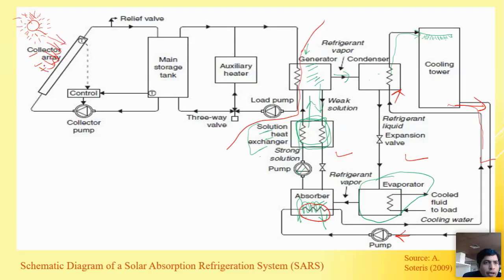After consuming this energy, the fluid which was moving inside the absorber tubes moves to the relief valve, and then this hot fluid, and actually I'm not naming the fluid because any fluid may be used. If it has very good thermal mass, or is non-corrosive and so on, we may take any other fluid. It is not necessary that we use water only.